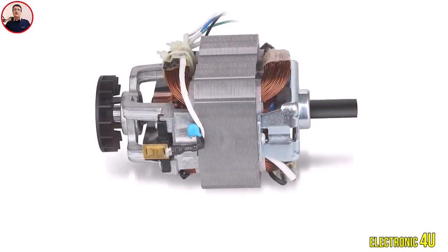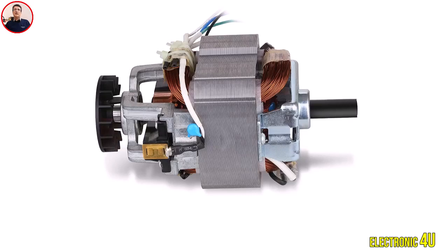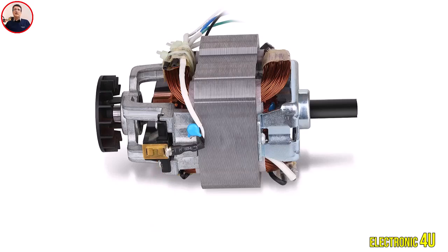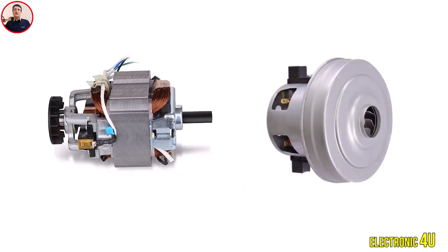The main difference is that a universal motor can work with both types of current, while AC induction motors only work with AC, and standard DC motors only work with DC. Also, universal motors use brushes to transfer current to the rotor, whereas common AC induction motors are brushless and work based on induction. Because of this ability to adjust speed with voltage, a Triac is often used to control the speed of universal motors in AC applications.